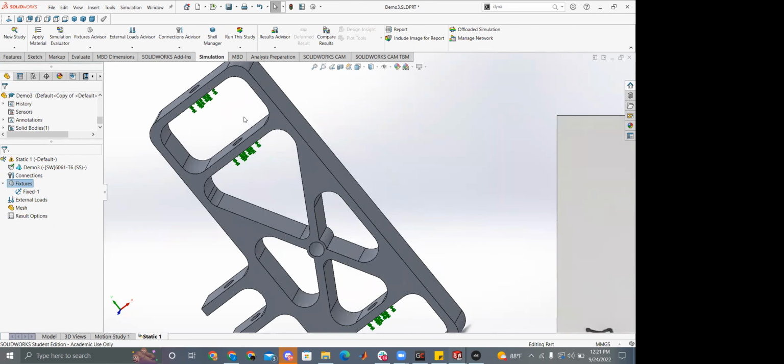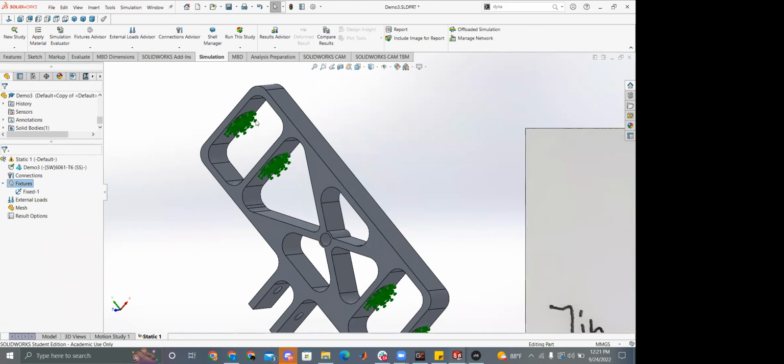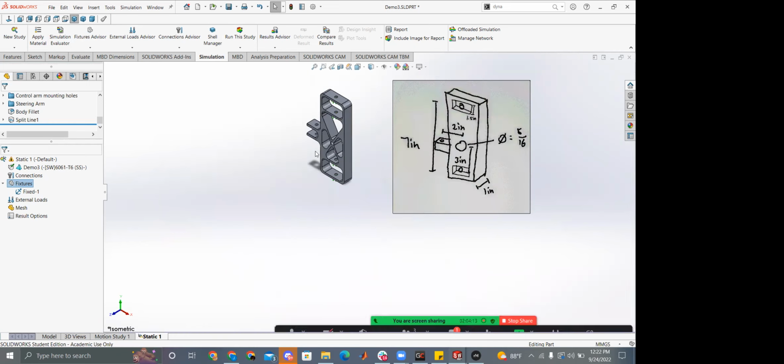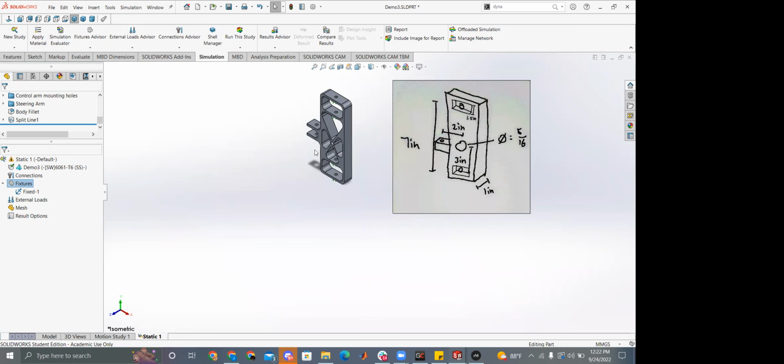As we can see here, this loading case is better, and these fixtures are better, but they're still not quite accurate, right? This is like if we glued the suspension to that upright and didn't let it turn and didn't let it move left to right on that face. Whereas if the upright gets pushed really hard that way, it's going to be those bolts that hold the upright in, not necessarily that bottom patch.